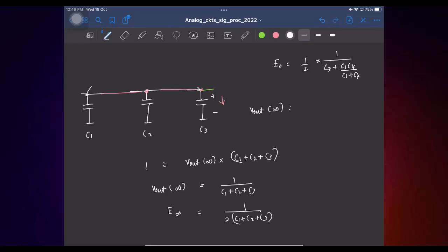Of course, with these two you can find what V out square is. We might have lost some charge? No, the charges will just get redistributed among the capacitors. If there is a path for the charge to get lost, it will. Since no capacitor has discharged at all, that is why we have equated it to 1. Otherwise we would not have done that. If there is some path to ground, all the capacitors will take that path and discharge. If there is at least one DC path to ground, you can always find a path from any capacitor to ground through the resistor.